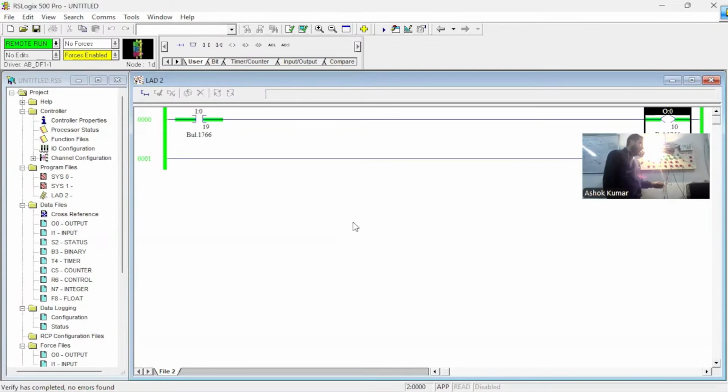It is giving us the logic without even sensing, but it gives you opposite logic. Without sensing, the output is on, but when it is sensing, the output is off. So I'm using one metal to detect. If I place the metal, it is giving us zero logic. And when I remove the metal, it is giving us one logic because it is working in NC. Okay. So let me remove this because it will create a lot of problems during the live. So let's remove it. Okay.